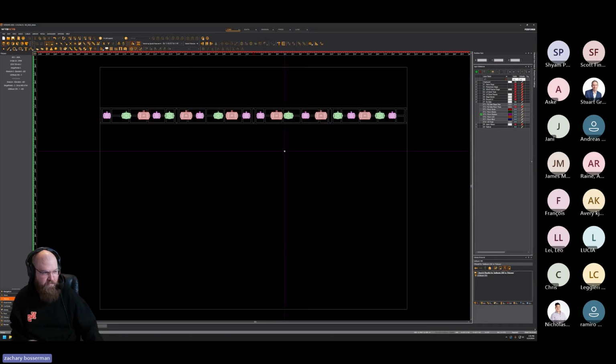Now's the part where I want to pay attention to fixture placement in a relative sense. I'm told this is where it's going to be. I need to get things at least looking good for when I'm prevising. So what I'm going to do is turn off the edit for the truss. I'm going to grab all these fixtures and hit Control-Shift-D, which is to distribute fixtures along a hang structure, in this case on my truss.